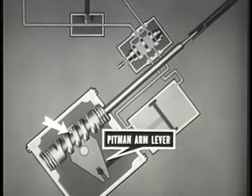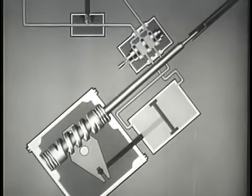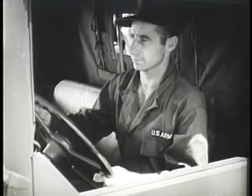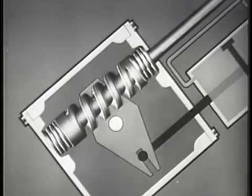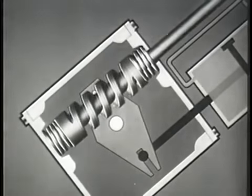When the steering shaft is turned, it requires a greater effort to turn the Pitman arm shaft and lever than to compress the springs at either end of the cam. This is so because the Pitman arm shaft and lever are connected to the front wheels. This action causes a cam spring to be compressed, allowing the cam to move up or down, depending on the direction that the steering wheel is turned.